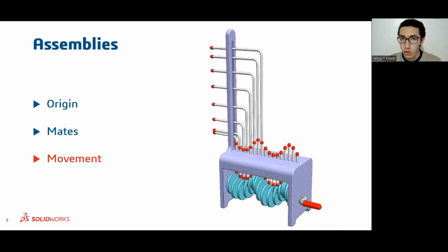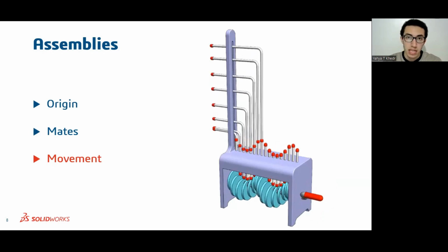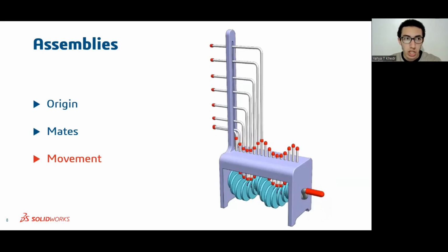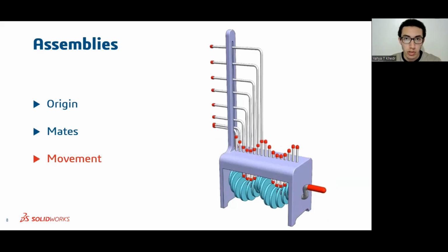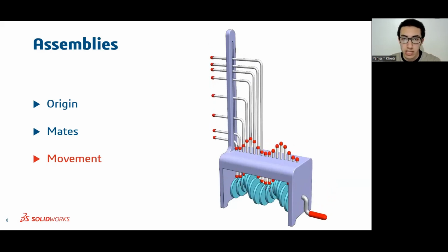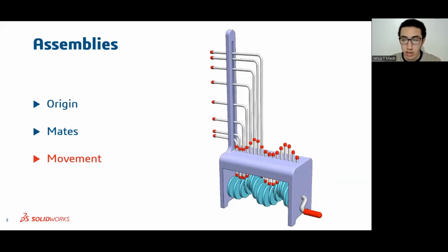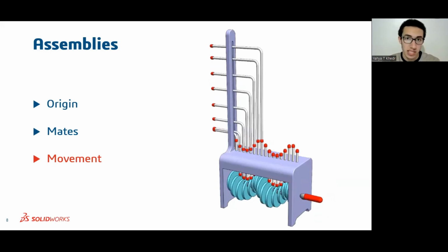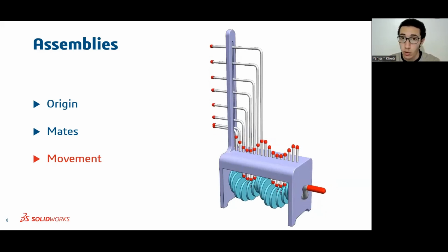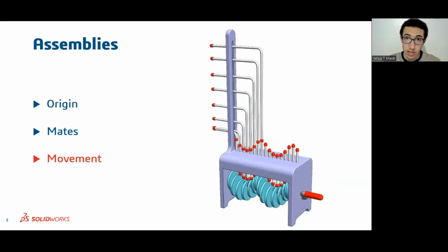And what I'm focusing on right now is that if you created the model and your initial view of that model is that it should move in a specific way, try to test that. All you have to do is grab a component and move it around with the cursor and see if the assembly, after you added all the mates, is moving as expected or not.